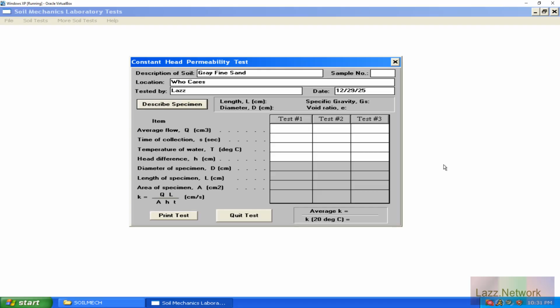So technically, this is where you're going to run into one of two different perm devices. You can have a perm device which, for most constant head permeability testing, requires manometer ports. It must have two manometer ports. And what the manometer ports do is measure what the head flow is in the sample itself. It's usually at the most center point of your sample.